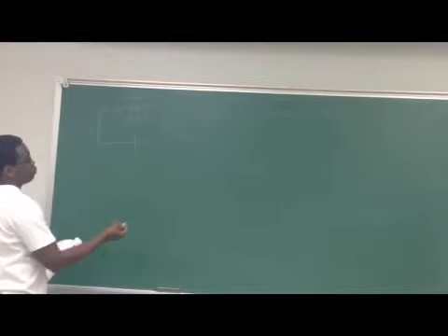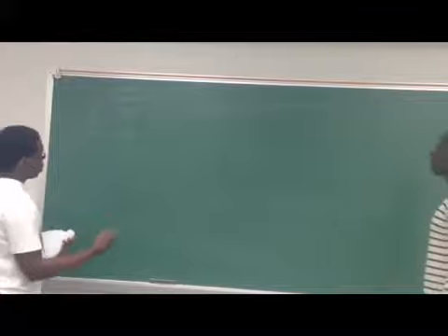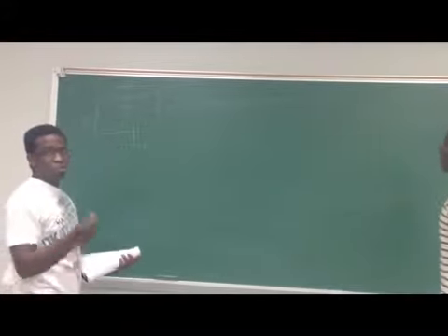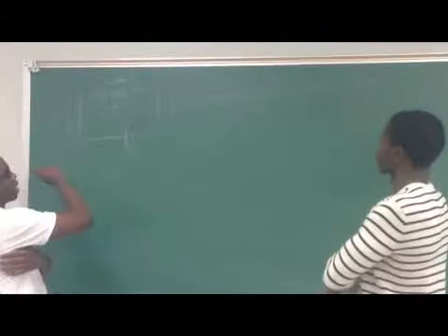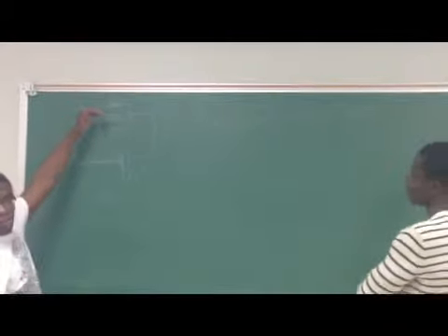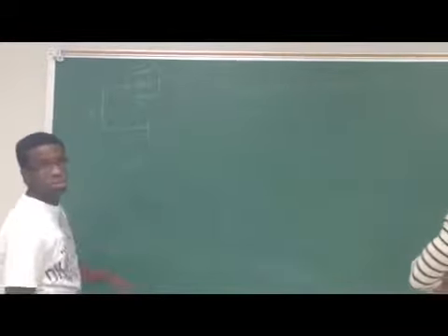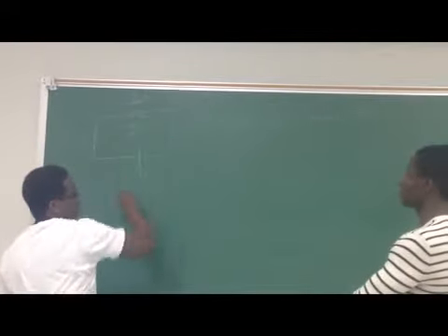So now, using Kirchhoff's voltage law to find the voltage in each resistor, all we have to do to find the current is just divide by the resistance. So to calculate the current across each resistor, since we already found the voltage, all we have to do is divide by the resistance at each resistor.